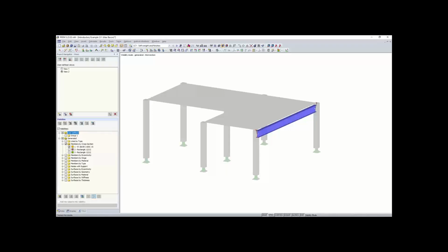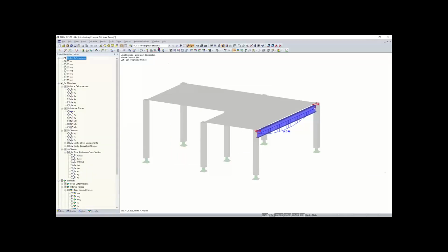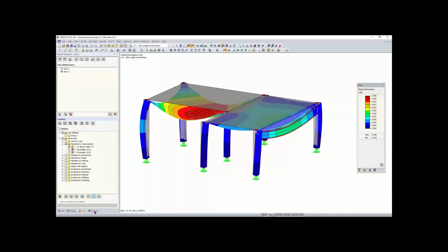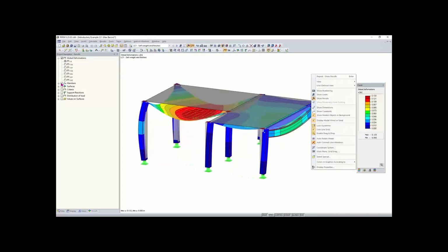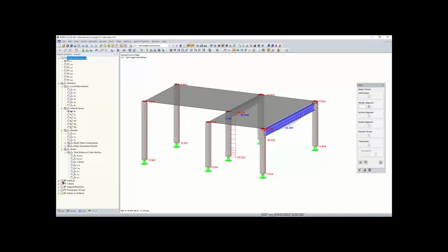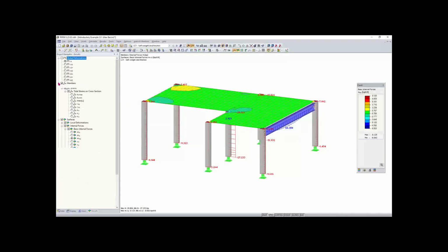The third tab we would have is our results tab. So if I just run the results for this model quickly, then we will see our results tab pop up at the bottom here, only if we have results run. So I just ran my load combination 1, and if I turn off my visibilities, now you can see in my results tab, this is again similar to the other menus where we have our expanding and collapsing folders. So right now I have global deformations checked off, and we're viewing our resultant deformations. And you can see we get a nice look at that, and then we can also check out our member basic internal forces, as well as our basic internal forces for our surfaces, if we would like. But we'll go over more of this in detail later, so don't feel too rushed to learn this real quick. We will be going over all of this in the training. But I just want to give a basic overview.